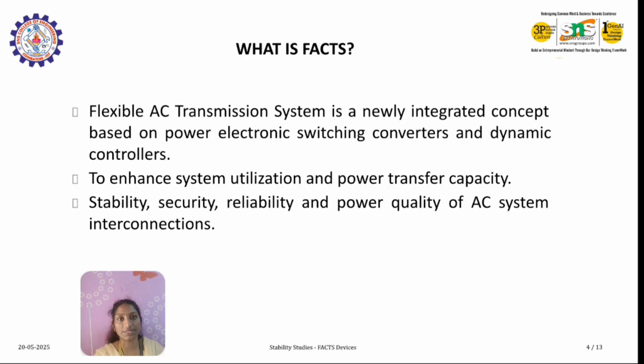Coming to what is FACTS: a flexible AC transmission system is a newly integrated concept, which is based on power electronic switching converters and dynamic controllers. It is a device we use to regulate the voltage and current at a particular place. The main purpose of FACTS devices is stability, security, reliability and power quality of AC system interconnections. It is also used to enhance system utilization and power transfer capacity.